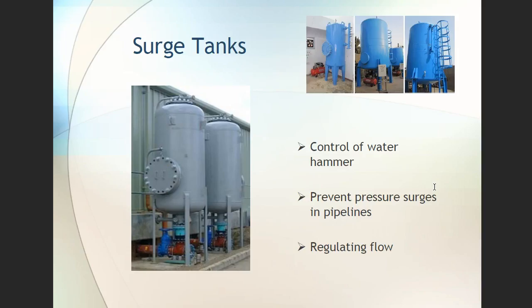Surge tanks. Surge tanks are basically, there's air in the top of them, and water in the bottom. Oftentimes there's a rubber gasket that goes in between, and it controls water hammer. And basically helps regulate the flow, and it prevents surges. It balances out that system. So again, it's kind of a shock absorber for those hydraulics. Anytime a pump starts or stops, fire hydrants. If somebody opens a fire hydrant really fast, it's the same thing. You can get water hammer going. And again, when exercising valves and hydrants, you always want to open them and close them slowly.